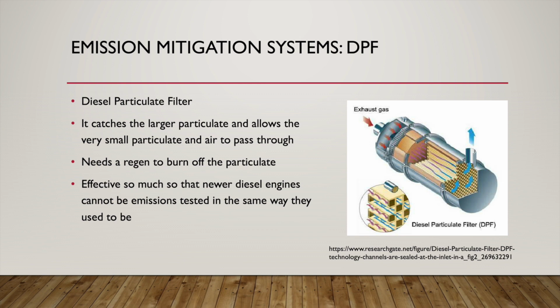But now what we do is we just use the engine control module to increase the exhaust gas temperatures. That gets it hot enough in there that we burn off the particulate. It's so effective that newer diesel engines cannot even be emissions tested the same way that they were before.